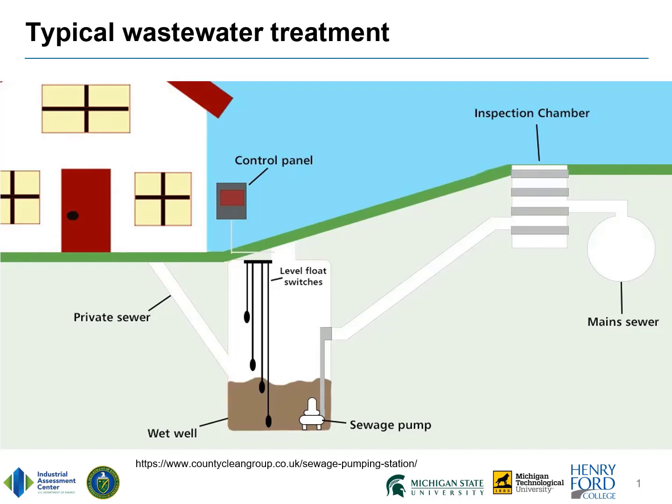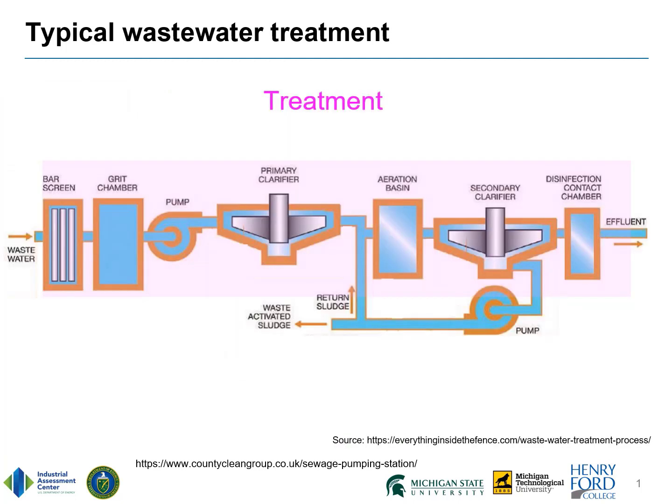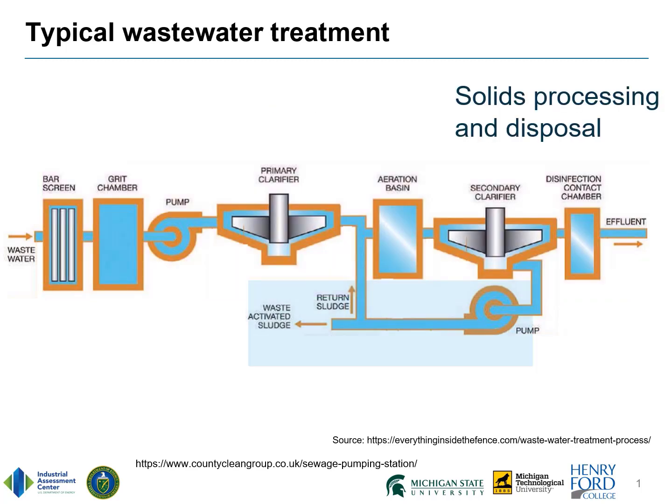The wastewater then flows through the treatment plant. Ideally, the wastewater would flow by gravity through the plant. However, that is often not the case and pumping is needed. In activated sludge systems, the aeration blowers are the largest energy users. The last part of the plant is sludge handling. Sludge must be pumped from the bottom of sedimentation tanks to the ground surface for treatment.